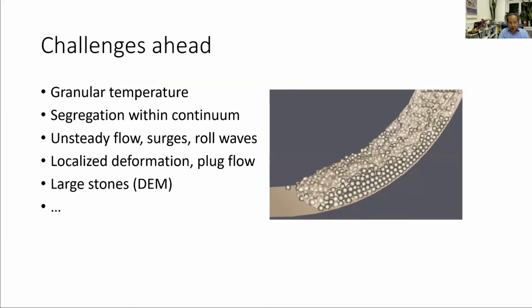So all these models do not consider so-called granular temperature. The granular temperature means how the granules, the sand particles, are agitated in the material. Most of the models also do not consider segregation within continuum, right? There is some very interesting work here. So, you know, you could reproduce the segregation with DEM. This is what we do in the drum. We did a drum test, and we did also some coupled tests with DEM and so on.